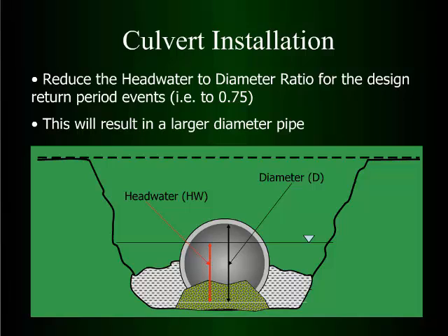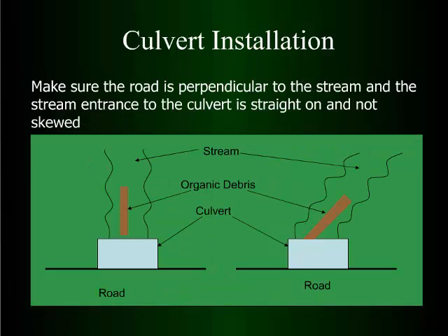I think one of the biggest benefits of the squash pipe is during normal flow where the water's down here, the diameter is wider on the squash pipe down here, and that probably has a lot to do with the plugging issues as well as having the miter on them. Having your pipe so the water hits the pipe straight on instead of at an angle, obviously it's a lot easier to jam stuff in if it's coming in at a skew on it.